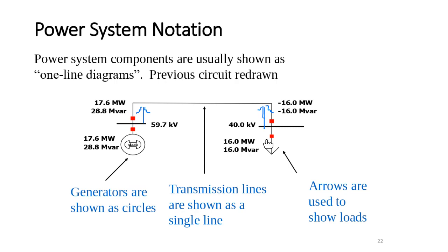Only the motors need reactive power. Machines need reactive power. The air conditioners have motors running, so they need reactive power. That is inductive load. If we don't have inductive load and we still have a capacitor here giving reactive power, therefore the reactive power will flow the opposite. So you will see the reactive power flowing this way and the real power flowing the other way.